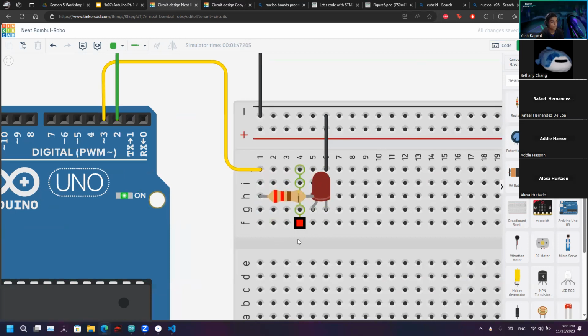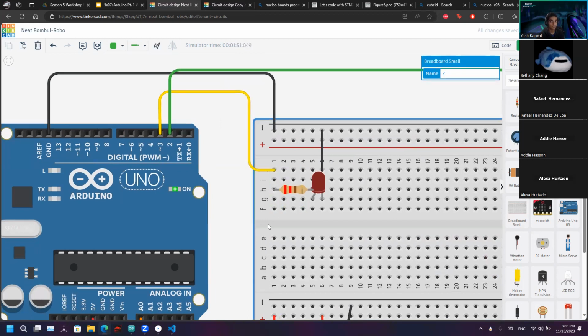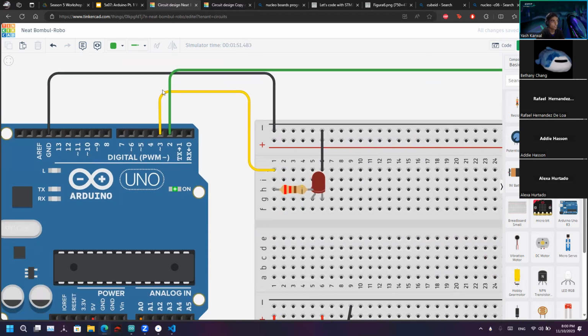Okay, so I understand how you connect the ground to the ground and then your voltage, but from the other end, going from your digital pin to your LED, right? Because I didn't see that at the beginning. Do you know how the breadboard layout is? Yeah. So it went from the pin down to this one here, the resistor, and then to the positive side of the diode. And then it goes to ground on the other one with just jumper wires.